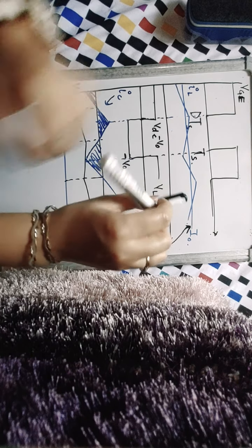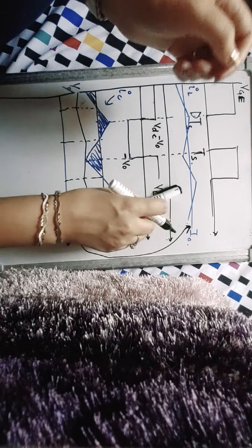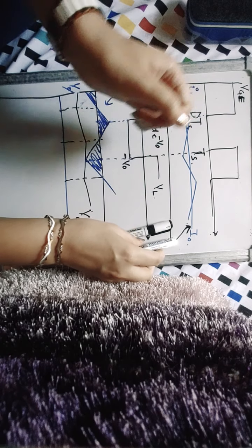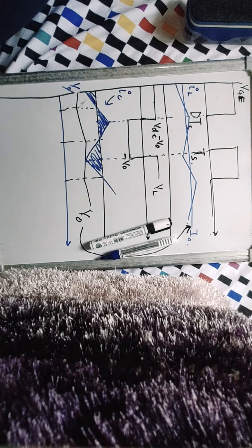Many people believe that the capacitor is the only element that determines the ripple in load voltage, but it is wrong. The inductor and capacitor together determine the ripple in the load voltage. The inductor also has a role to play there. In fact, this was one of the questions I was asked in my interview at IIT: is it just the capacitor, or does the inductor also determine the output voltage ripple?